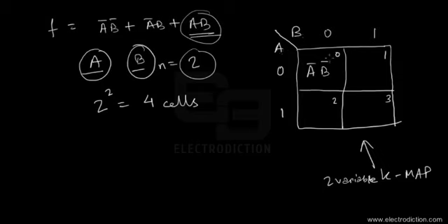Okay, so following this particular convention, the other cell over here, that's cell number 1, should have a minterm combination that should look something like a bar b, where you can see the value of a is 0, so it's a complementary variable, whereas the value of b is 1, so this means that it's a non-complemented variable. So as I said, I repeat that in an SOP format of representation, a 0 always means a complementary variable, whereas a 1 represents a non-complementary variable.